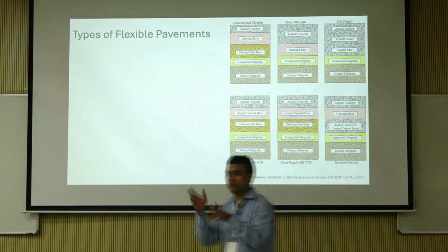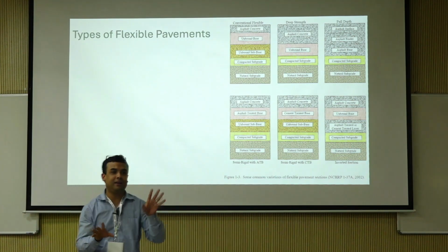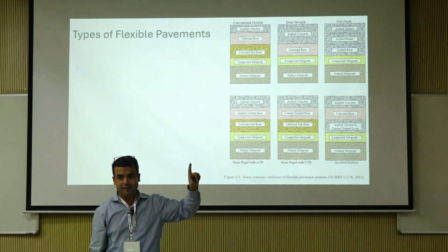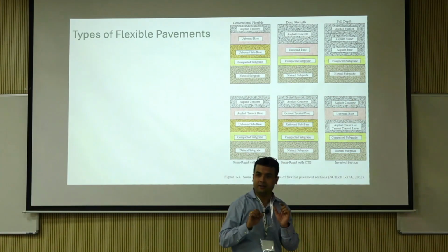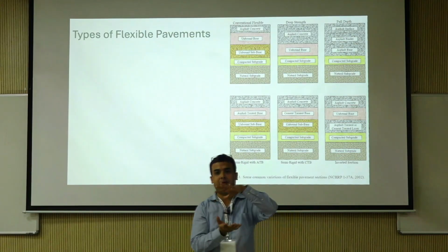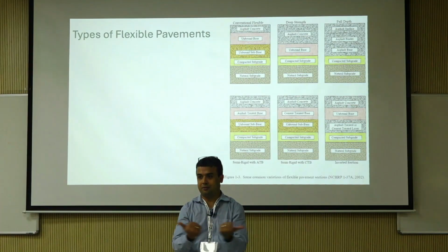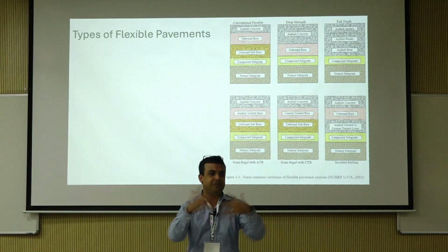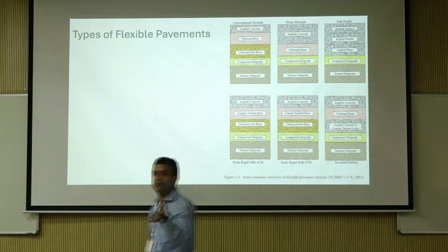How does a pavement die? Fatigue cracking, rutting. There is something called top-down fatigue as well, but mostly traditional physics says it is bottom-up. So now you have a good enough layer at the bottom, it's rich at the bottom, so even if it's a big strain, because it's rich, the modulus is low, it doesn't crack anymore. And for the rutting, you have a rut resistant layer.